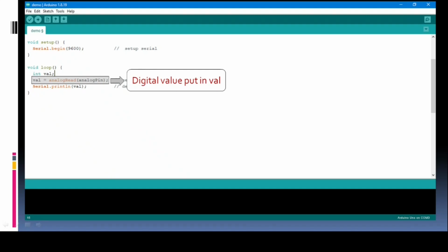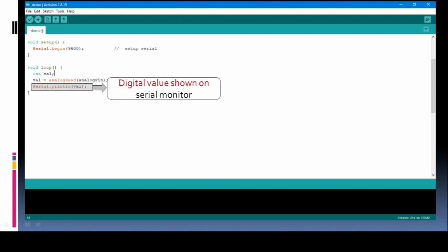Here you can use the analog pins A0, A1, A2, A3 and A5, and we show the value on the serial monitor. If you did not connect anything to the particular pin which you want to use as an analog pin, then this will show some fluctuating values. When you connect any source to that pin, then this will show you a stable value.